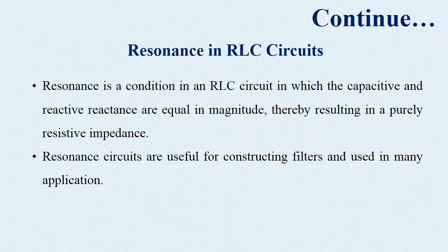What is resonance in an electrical circuit? Resonance is the phenomenon at which the response of the circuit is maximum for a given particular frequency. This response will be seen in the electrical circuit because of the capacitor and inductor. Both the elements have the ability to store energy. Due to this, even if we remove the voltage source, the inductor will continue to supply current to the capacitor, and through this current, the capacitor will charge.